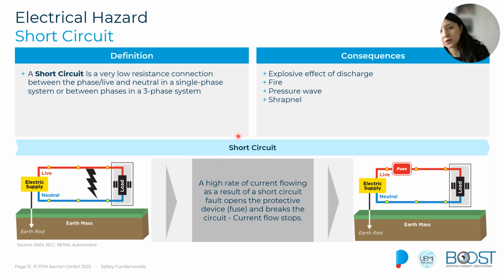In order to prevent all of those, there are many ways to avoid that. For instance, again, to have visual inspections to check that the cables are not damaged, that we don't have loose connections, and that we are wearing all the insulation that is required. Also, we need to have the proper standards for what materials should be used, and at which distance the conductors should be, to have a safe design.